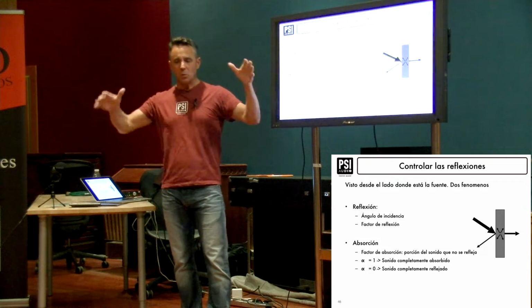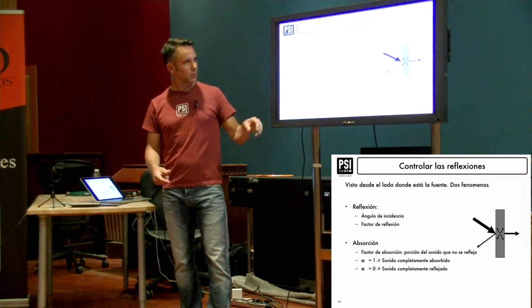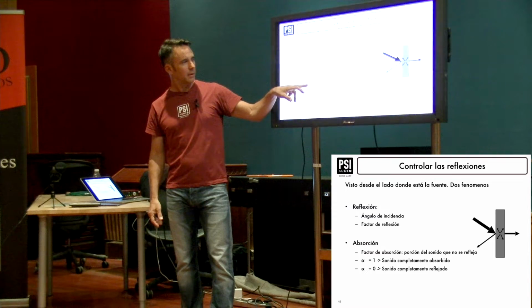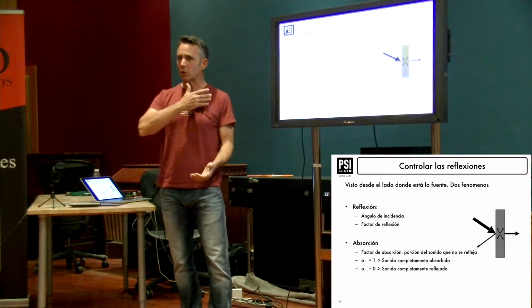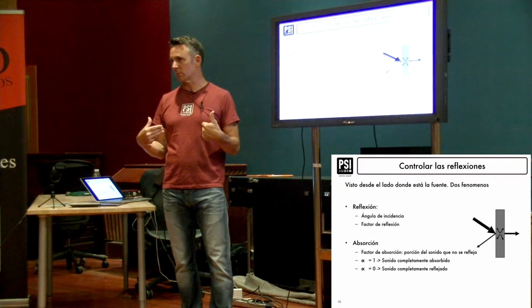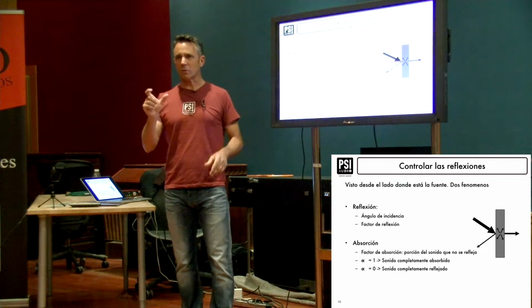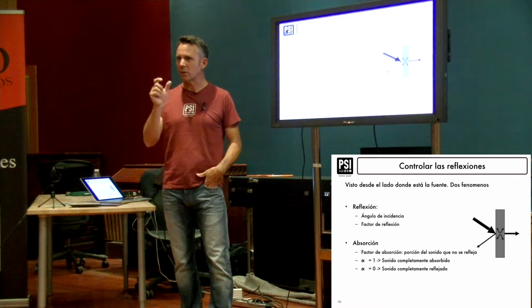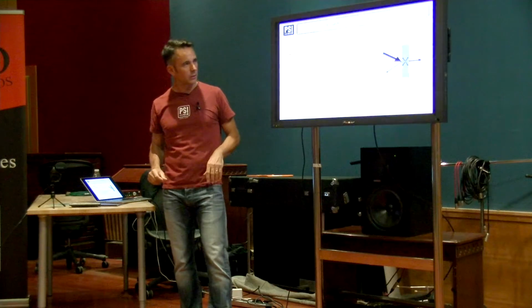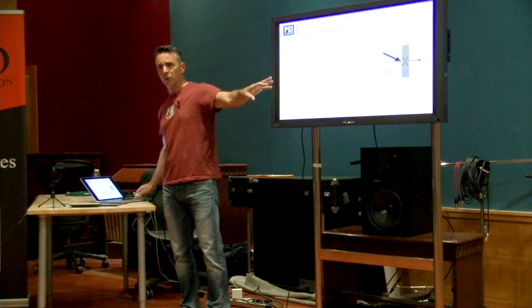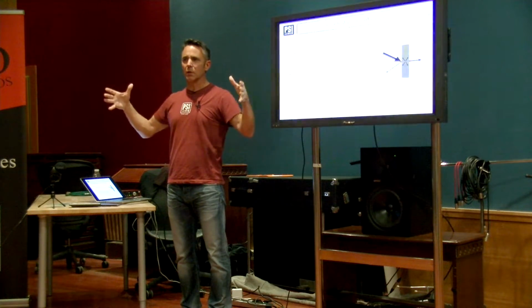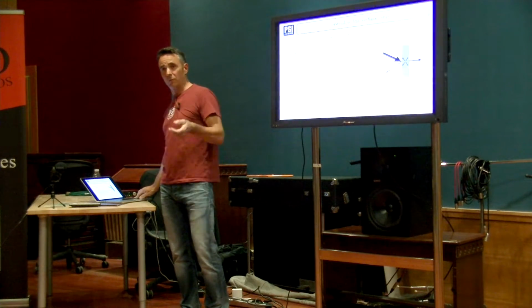And basically, 1 square meter of absorbent with an alpha Sabine of 1 is the same as just opening 1 square meter and all the sound goes out, nothing comes back. Okay, and you can get to things that are quite close to 1 with just passive absorption. We'll see that. This you're all familiar with. So just think of the alpha Sabine as being the equivalent absorption area of a perfect absorber.